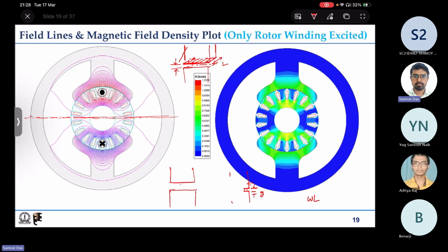So the flux lines probably at the middle, they will still be crossing like this, but as the lines tend to go on the two sides, they will tend to bulge out. That is how the actual flux line distribution would be. So in this case, it is not straightforward to calculate the area.